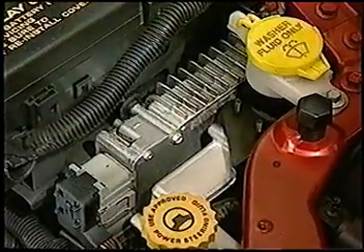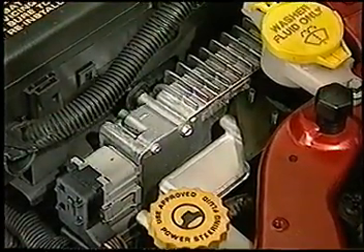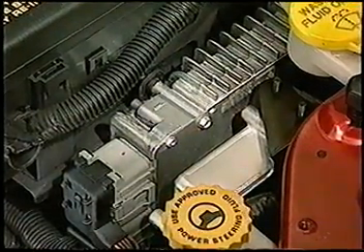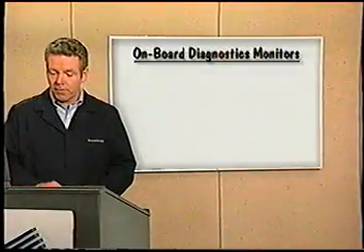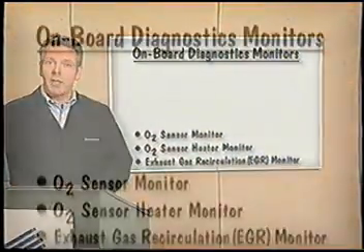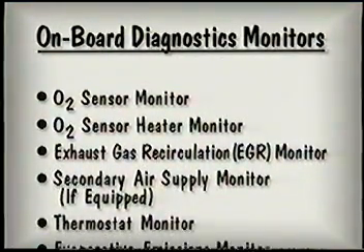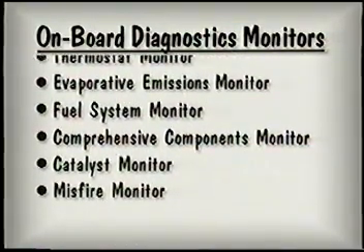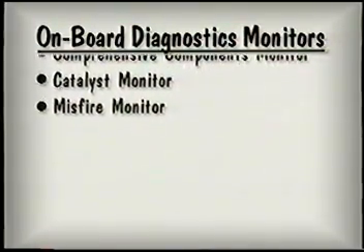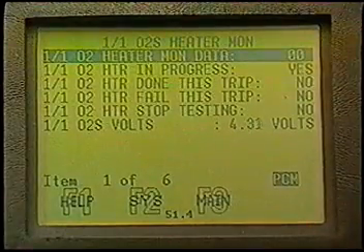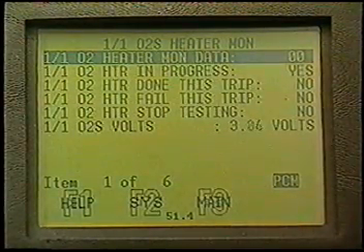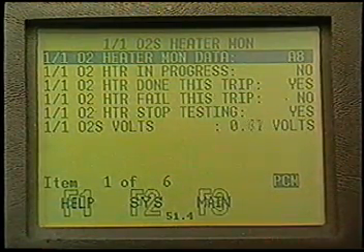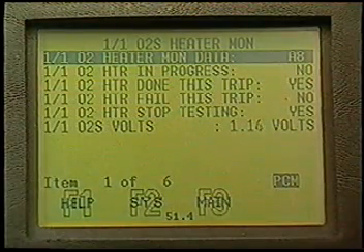As I mentioned earlier, in onboard diagnostics, the task manager runs a series of diagnostic monitors to test, detect, and identify emission-related faults in the vehicle. All of the monitor tests vary in length and are run by the PCM as soon as enabling conditions have been met. Some of the monitors will be performed only once per trip, while others will run continuously throughout the trip. Once per trip monitors run when enabling conditions are met and may conclude at any time. Once the monitor concludes, it will stop and the results are recorded in memory.